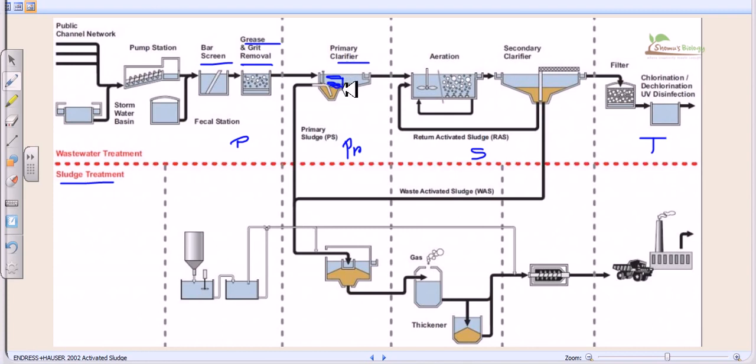And the second layer or second system which is placed here, which is also rotating, is actually slightly rotating at a very low velocity, and as a result of this rotation, it helps all the small sediment, all the small particles to settle in the lower region or lower tank or reservoir tank of this primary clarifier, which is called the primary sludge.